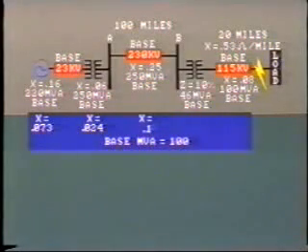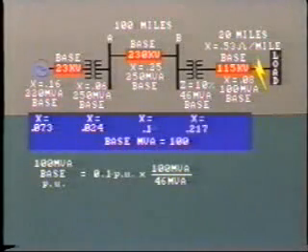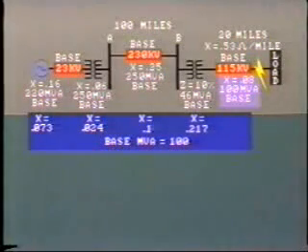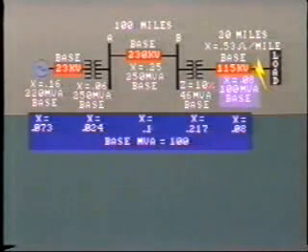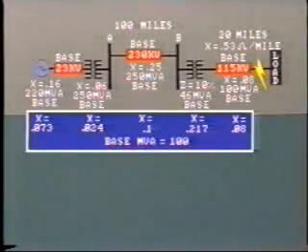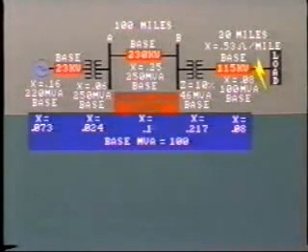We already know the impedance, let's call it reactance value, for this transformer, 10% at 46 MVA. That is 0.217 per unit on a base of 100 MVA. The 115 kV line we already calculated as 0.08 on a 100 MVA base. So, what do we do now with all of these 100 MVA base values of reactance? Well, as the fault is at the end of the line, summating gives us a total per unit reactance to the fault of 0.494. And remember, this is calculated on a base of 100 MVA.